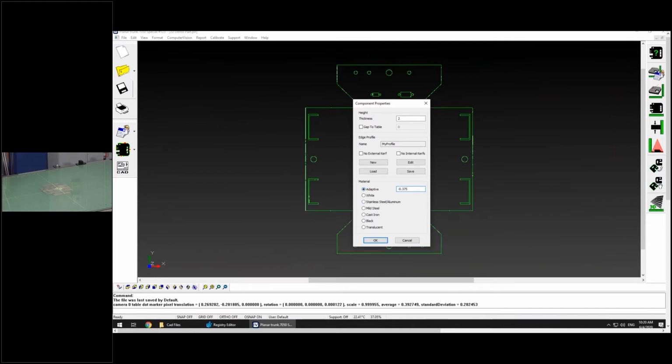And now we basically comp that part in this machine to the CMM and know that our values are going to correlate very well. The downside to this is you have to almost do this with every part, which is slow. But the upside is now you're correlating your data to a very, very high accurate machine, and you know that the parts you're getting in this machine, if they truly are out, they've now changed from your master nominal, and that's why they fail.